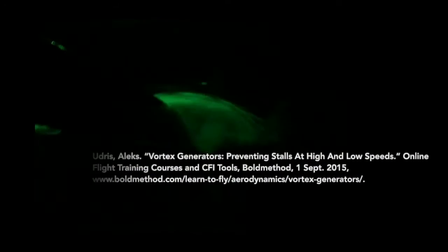This video describes the airflow that is seen behind the cylinder with the trip strips in place at a wind tunnel speed of 6 meters per second. In our MATLAB code, we talk about the separation zone being moved by 7.5 degrees at 15 meters per second. In this video, it can also be seen that the separation zone has been moved because of the trip strip. However, it is not exactly the amount in the MATLAB code because the code is based on a different wind tunnel speed. The trip strips act similarly to vortex generators, which are seen on cars and planes.